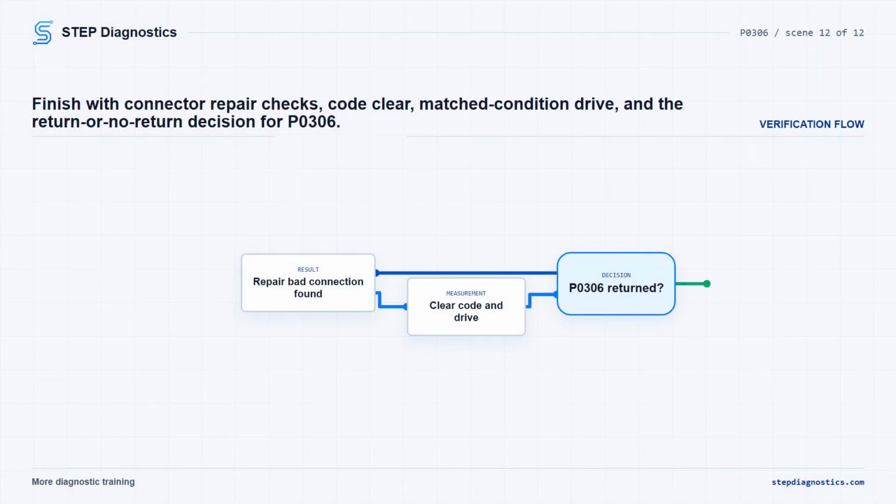If the earlier checks have not isolated the cause, disconnect the PCM connectors, related inline connectors if equipped, and related component connectors. Inspect connector installation, locks, corrosion, water intrusion, weather seals, bent terminals, overheating from poor connection, push back terminals, spread terminals, and terminal tension. Repair any connection issue you find. Then reconnect the PCM, inline, and component connectors, making sure everything is fully seated and locked.